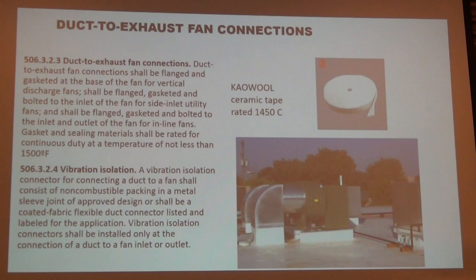Once in a blue moon I come across this, have you seen this, Mark, that foam rubber gasket they try using, which is combustible. As long as it's rated to 1500 or higher, you could use it. The foam I did, I took a piece of it and lit a match to it and it caught on fire. I've seen them, they do have a listed one for 1500. Do they? Yes. And they're listed for grease resistant too? It says just temperature ratings on it. Okay.